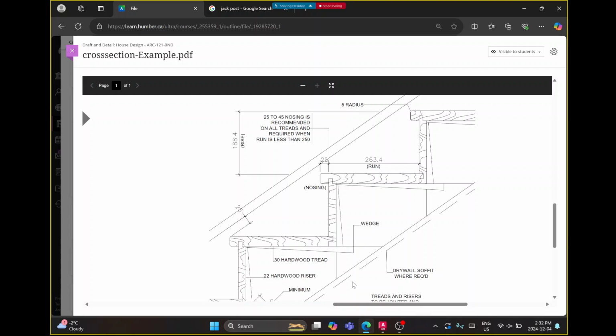Usually what happens is they create shop drawings of what you draw that shows all of that detail. Then they send it back to the architect to verify, not that all of the notching and stuff is correct, but that the parts that they designed are correct, to make sure this distance didn't change. So in a nutshell, they add a bunch of detail that tells you how they're going to build this thing, and your job is to verify that it still operates the way you intended. I don't know if that makes sense. I know I'm going way ahead here.